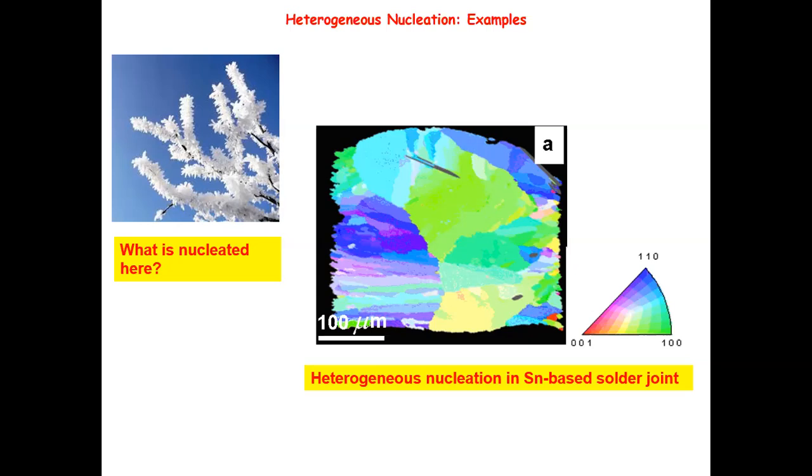And because the temperature is very low, within these water droplets there is heterogeneous nucleation of small ice nuclei, and then these ice nuclei start to grow, and then you see this very nice, interesting thing. So this example actually illustrates two different types of heterogeneous nucleation. The first is that vapor uses the tree branch to heterogeneously nucleate into water droplets on these tree branches. And then within the water droplet, small ice starts to nucleate in a heterogeneous manner and begins to grow like this. So I think this is a really cool example to illustrate heterogeneous nucleation.